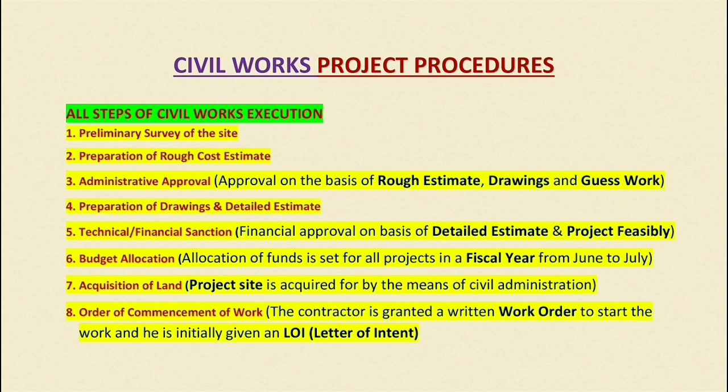Afterwards, the drawings and the detailed estimate are prepared. Once we have the administrative approval, the detailed drawings are prepared in AutoCAD, and the detailed estimate is prepared from these drawings. First the drawings are developed, and then from the drawing measurements we develop the detailed estimate.